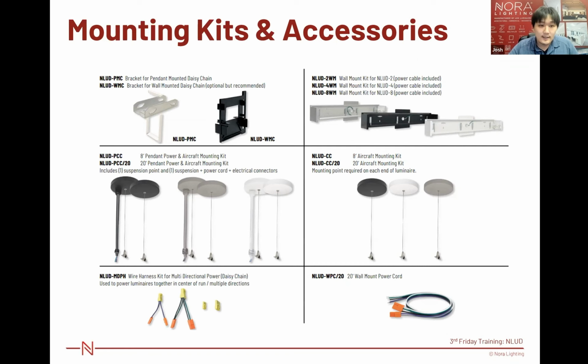So first, NLUD-PMC and NLUD-WMC, those are required when you are doing daisy chain. And NLUD-2WM to NLUD-8WM, those are needed when you are doing wall mount. And NLUD-PCC or NLUD-CC is needed when you are mounting on the ceiling as a pendant mount. So PCC stands for power cord, and CC is just an aircraft cable.